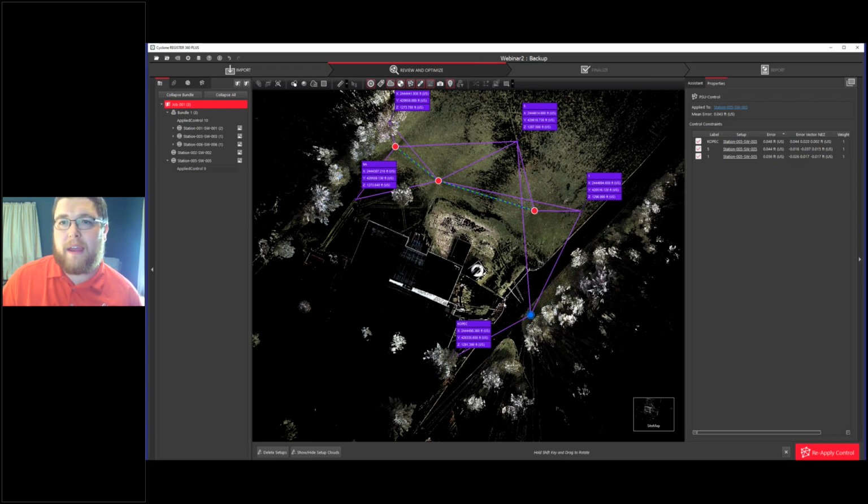So you can see here for Scan World 5 how my control points tie in and my mean error versus the control that I used from that scan. Same thing, I could do that on this one. So I'll sort by my Scan World, and I could check how the residuals are for every single scan here.